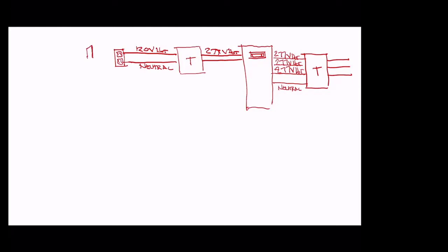So if you have your computer and your CPU, these are going to plug into the electrical receptacles at 120 volts because that's how they operate. Now, we're going to have our lighting on another circuit, and for our lighting, we'll have our circuit breaker like before. But for our lighting, instead of delivering 120 volt, we're going to deliver 277 volt hot to the lighting and a neutral for this branch circuit.